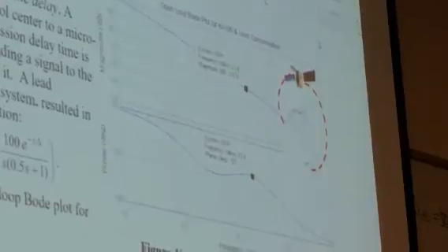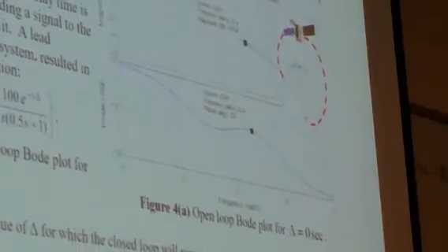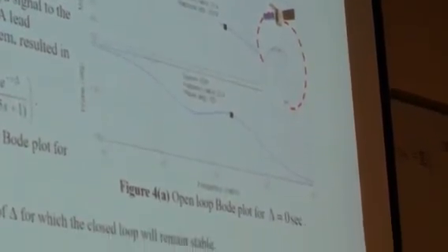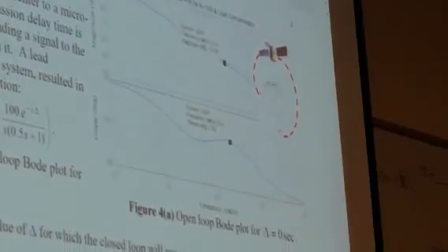So what you have here is you're going to address the importance of frequency response phase in the context of time delay. As I told you before, most mechanical engineering problems, they don't care about phase. But you guys in Aero have to care about phase immensely, because phase drops lead to instability, and you guys have time delays.